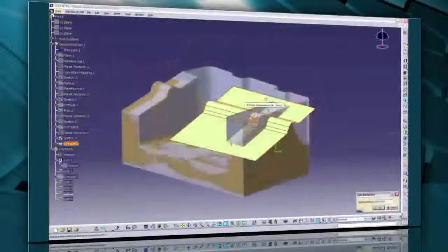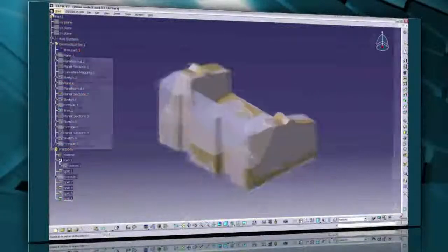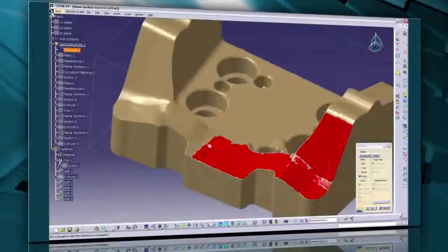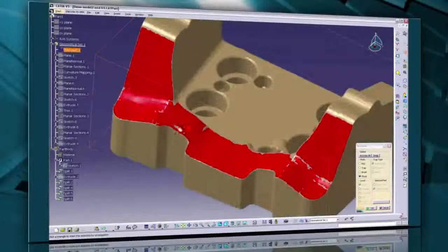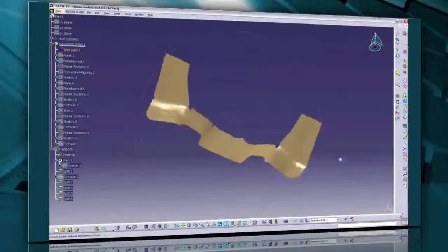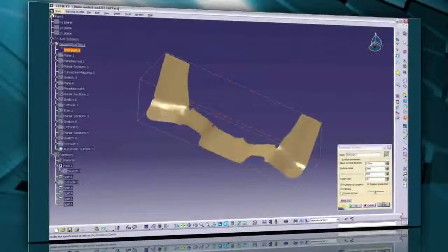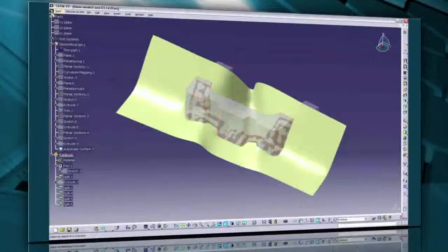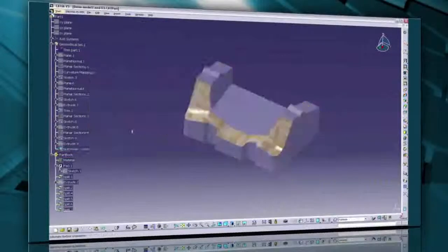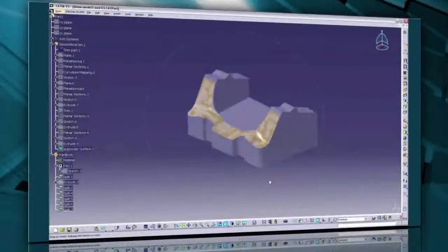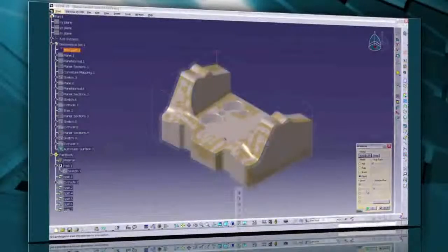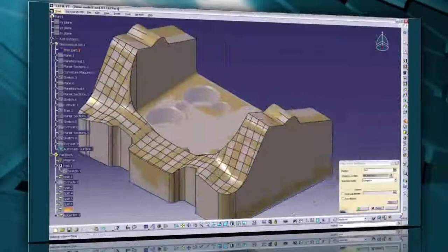For complex surfaces, QSR has tools to reconstruct them by quickly approximating the shape with a brush-like tool or flood selection. The surface does not need to be perfect. Then, using an automatic surface tool in QSR, the resulting unlimited surface is created and is usable as a splitting tool on the part design workbench. After the main surfaces are created, you can use the usual tools of part design for the remaining operations. Easily create missing fillets and add features like holes and pockets.